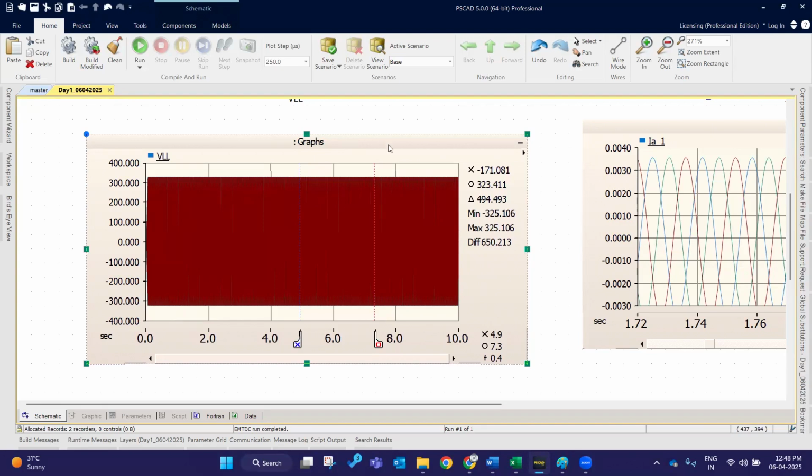If I explain the graph options alone, there are various options inside, right? See here, all are basic: zoom in, zoom out, resetting the x-axis, resetting the y-axis. This is complete reset, so instead of this reset, we are pressing R. This is previous zoom.